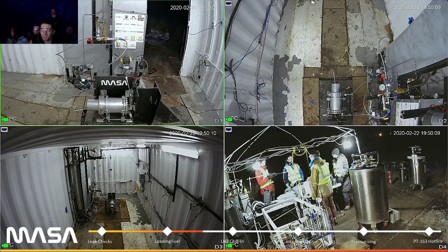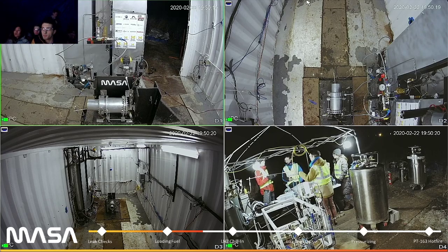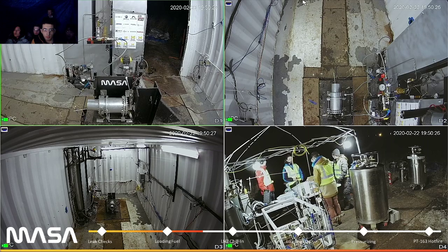The alternative is having a pressure-fed system where the tanks are able to hold the full pressure that the engine needs, so the tanks just feed the full pressure right away. Whereas if you had a pump, you could have the tanks at a very low pressure, and then the pumps would increase the propellant pressure into the engine. That's how most industry rockets are configured.